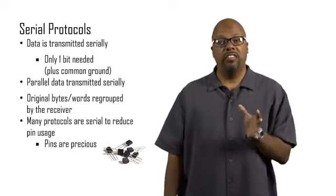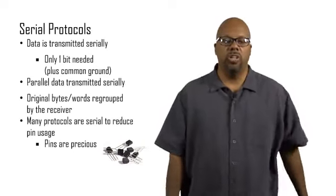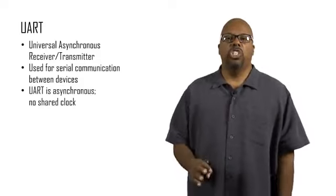Now, there are several different serial protocols. We are going to focus on UART. UART stands for Universal Asynchronous Receiver Transmitter. It is an old protocol, still useful though. It's used for serial communication between devices. It gives you long distance, actually. It's asynchronous, meaning no shared clock.